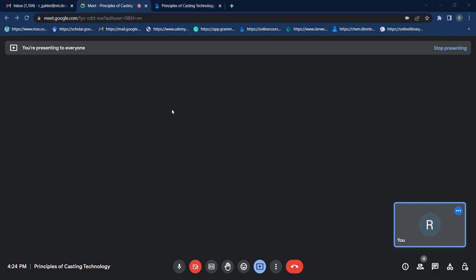In case of high sulfur content in steel, it produces a negative effect on the mechanical properties. Basically they form sulfides, leading to crack formation and fatigue failure. They reduce the fatigue resistance of the material, which results in a reduction of intergranular strength and also lowers the melting point of the steel, because they form sulfides. Okay, then can you comment on problem number 13?